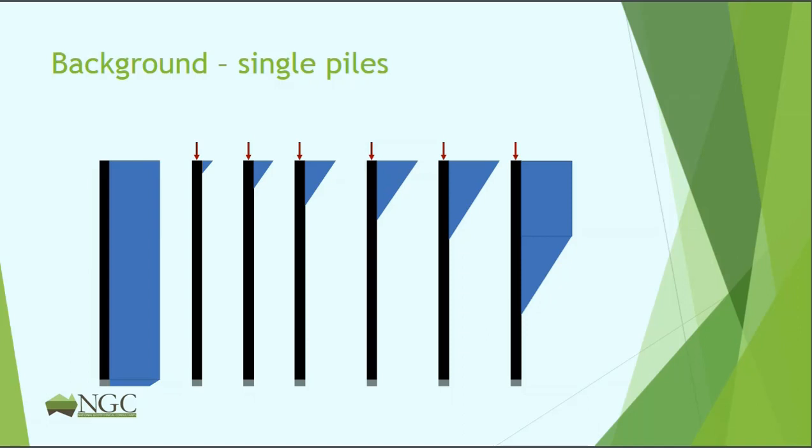You've got the same load on the top as you've got at the bottom of the liner because there's no shaft friction, and then you've got a little bit of shaft friction and some end bearing in this 0.5 meter deep socket. That's the design. But what happens in practice?